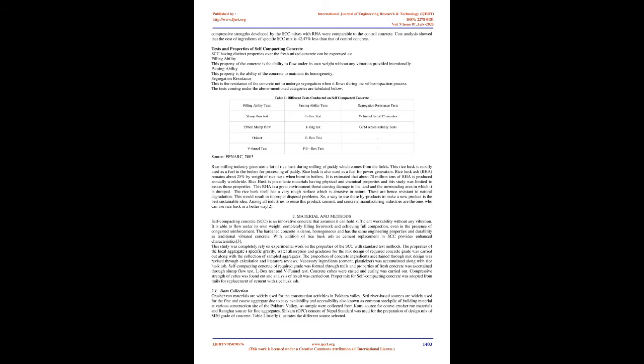Self-compacting concrete with a similar water cement or water binder ratio will usually have a slightly higher strength compared with traditional vibrated concrete, due to the lack of vibration giving an improved interface between the aggregate and hardened paste. The concrete mix of SCC must be placed at a relatively higher velocity than that of regular concrete.